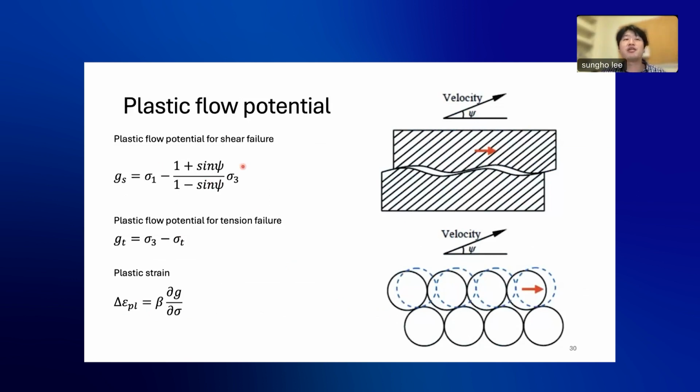And theoretically, shear motion cannot cause a volume change, but it occurs in reality. This phenomenon arises from the presence of asperities and grain rearrangement under shear loading. To account for this effect, I also introduced the dilation angle chi, which is generally smaller than the internal friction angle.